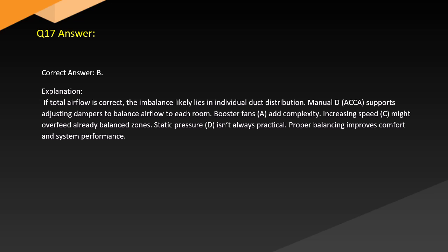Booster fans (A) add complexity. Increasing speed (C) might overfeed already balanced zones. Reducing static pressure (D) isn't always practical. Proper balancing improves comfort and system performance.